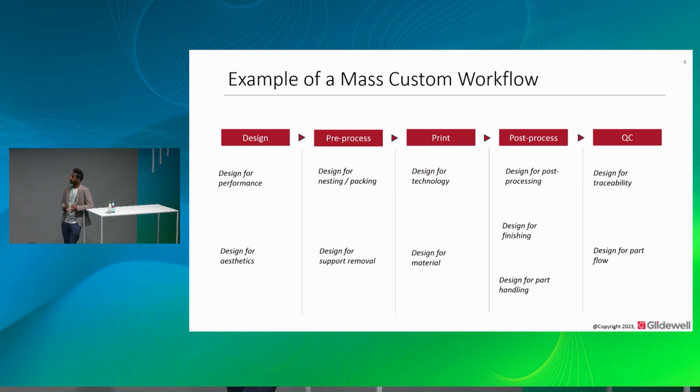So that's really the core takeaway from a lot of these design elements. We've added channels to improve the depowdering and make that more effective. We've added a couple of hooks and features to make sure that they're uniformly spaced out and we're getting optimum results from our vapor smoothing process. And we've also added grooves and inner mating components to make sure that we can actually interface with any of the fixtures and the QC processes that we have. And of course, we added the tag at the end that gives us the part ID for traceability.